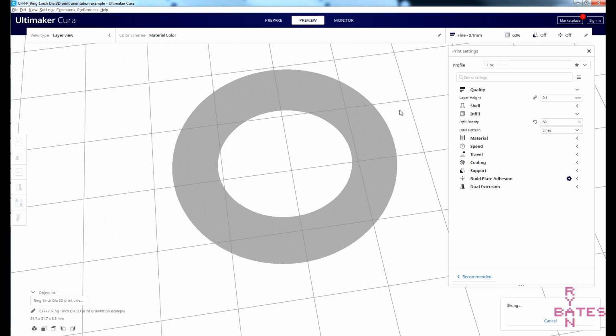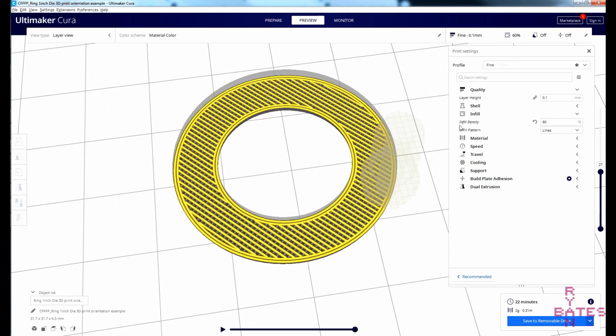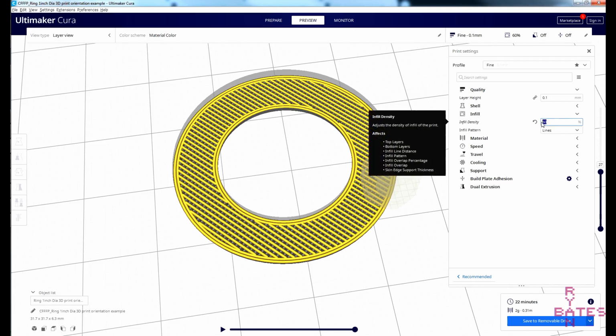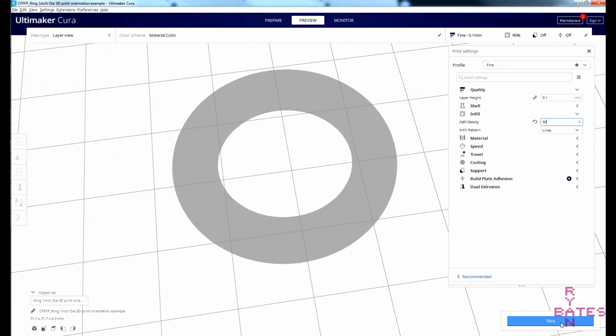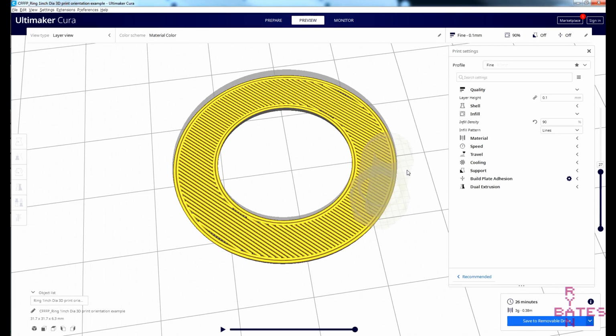Infill patterns are automatically generated by the slicer, though some slicers give you other options here. Cura, for example, has a wide variety of infill patterns left best for you to experiment with. However, the default infill pattern will typically work for most parts. Experiment with different infill percentages.